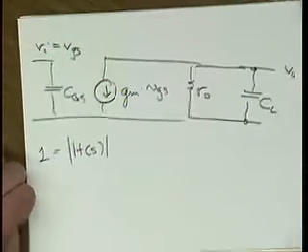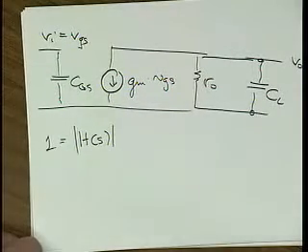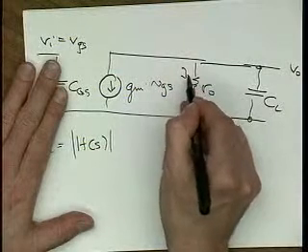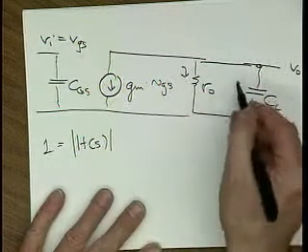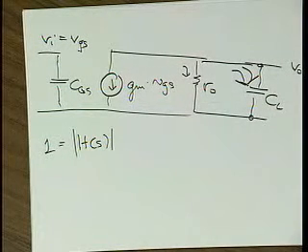Right? Well, we know at low frequency, this is going to be 100 or something like it, big anyways. And at low frequency also, all the current flows into this resistor here. Ultimately, this drops all the way down to unity, right? And then we get interested in that, because that's FU. So why does this thing suddenly drop all the way from 100 to just unity? What happens to the current? Well, all the current suddenly, at higher and higher frequency, like a torrent, flows into CL.